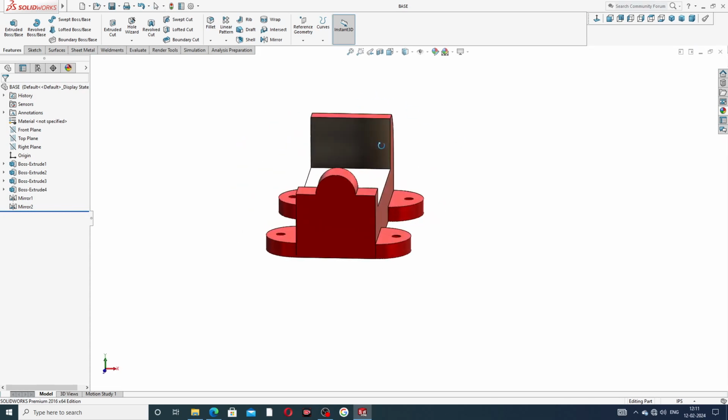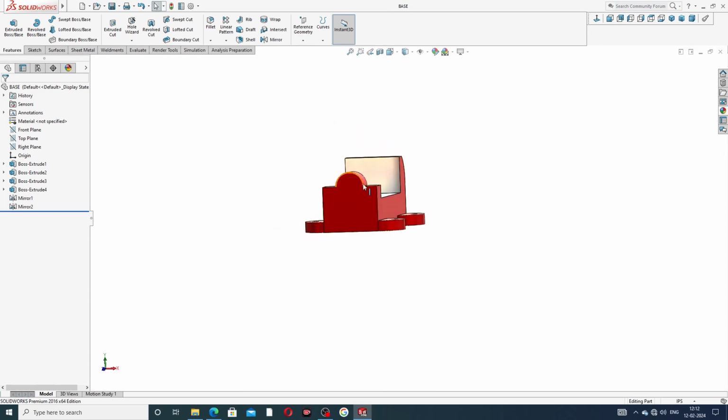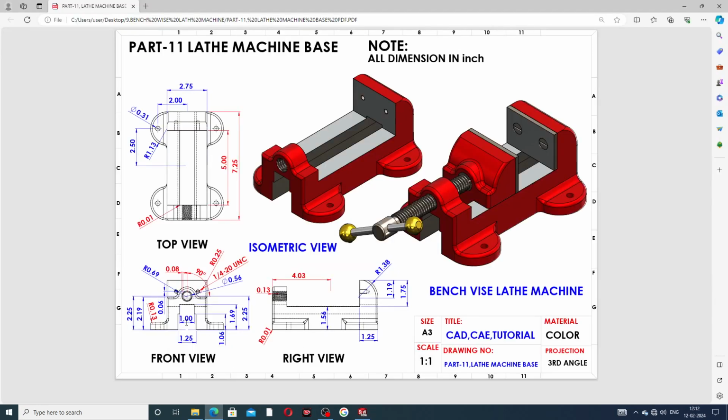Okay, all is perfect, drawn here, and select this. Next part is this, going to a cutout. The cutout is perfect. Select here. Okay, next part is this, going to a cutout. This portion is cut out, and this is 1 inch, and this is 1.25 inch, and this is 1.06 inch, and this is 1.69 inch. This portion is cut out here.